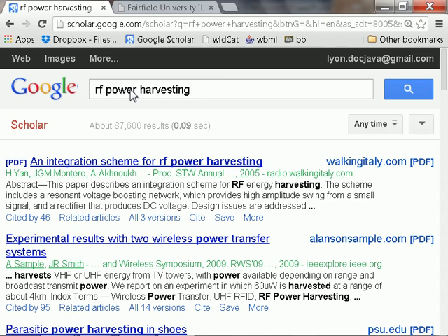And then the question becomes, what frequency should you use? What antenna design should you use? Whether or not you want to use something that is an unlicensed power, or whether you want to use just the ambient RF energy around you. Some people use UHF stations because they're so powerful and they're already there, and they can just pick them up. So there's a substantial number of different places where you can use these sensors.